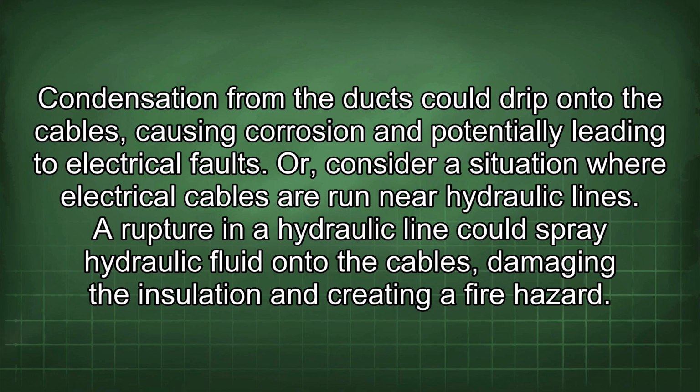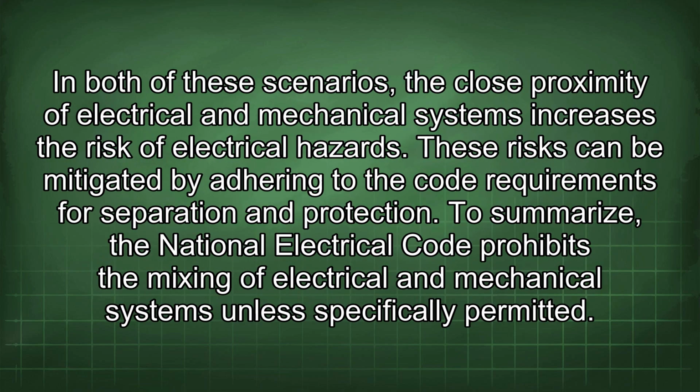Or consider a situation where electrical cables are run near hydraulic lines. A rupture in a hydraulic line could spray hydraulic fluid onto the cables, damaging the insulation and creating a fire hazard. In both of these scenarios, the close proximity of electrical and mechanical systems increases the risk of electrical hazards.